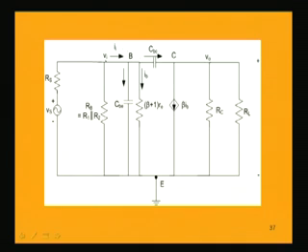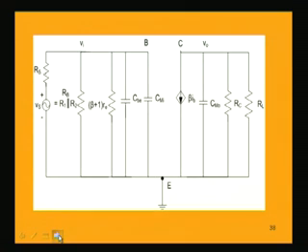This point is nothing but having the voltage Vi, and this point, the collector, is having the voltage V0. So, let us do that. We are distributing the capacitance CBC, which was here, into two Miller equivalent capacitances, denoted as CMI and CMO: the Miller input capacitance and the Miller output capacitance.